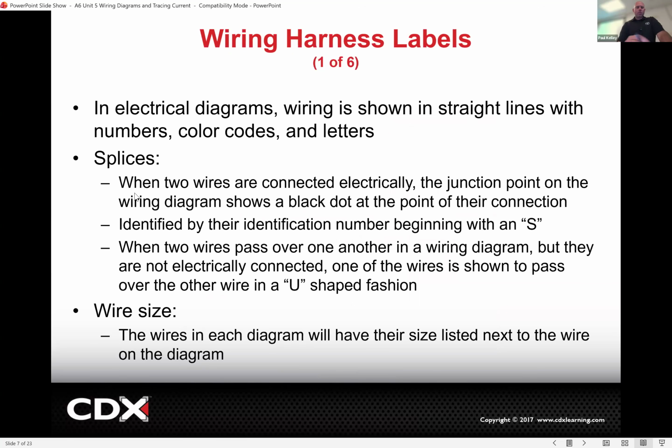Now, sometimes on the wiring diagram, it'll look like this. If you have a wire like this and this other wire, let's do it in color because some of the new diagrams are full color. They're pretty cool. You have a wire coming over like this. If they're different colors, it's a good chance they're not going to be spliced. Sometimes it'll do this little hop over thing, whoop, like that. If you listen really carefully, you can hear the noise that Nintendo makes when Mario jumps. That's what it does. It does help. Those are definitely not connected.